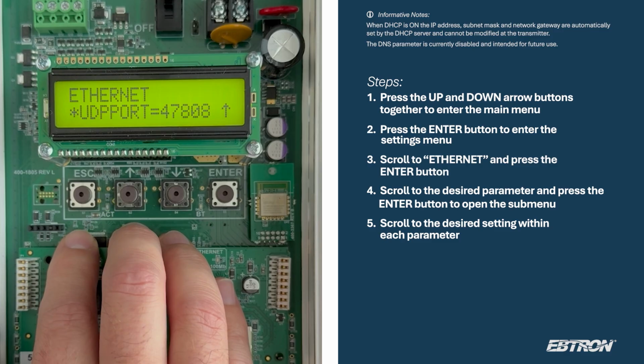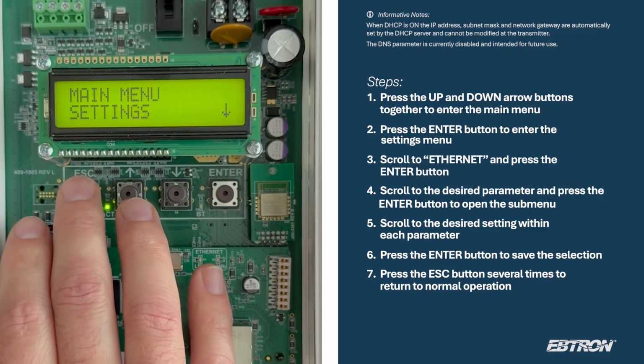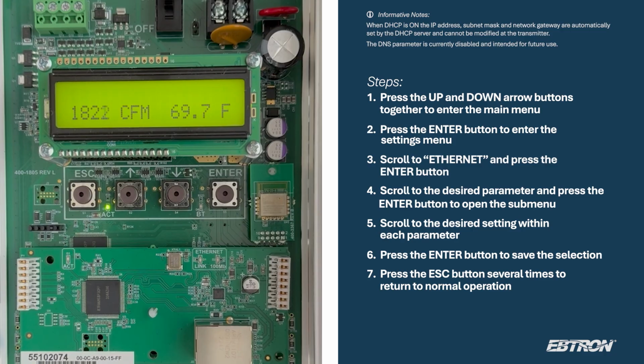You can make desired adjustments to each setting by pressing the enter button to select the parameter, then use the up or down arrow buttons to toggle between the available options. When finished with each setting, press the enter button again to save your selection. The new value will appear with an asterisk, confirming the change. You can then scroll to the next setting as desired and repeat the process. Once you are finished, you can then press the escape button several times to return to normal operation. That's it. You've successfully configured the Ethernet network settings on your EBTRON transmitter.